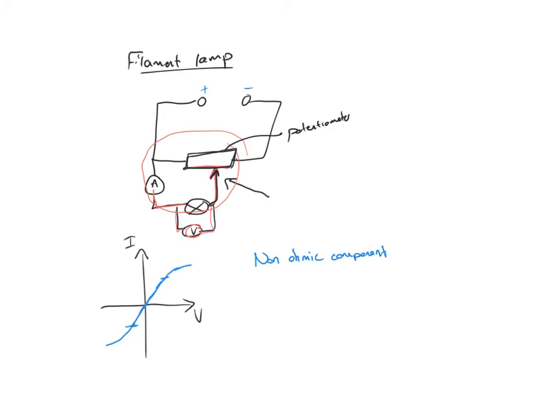And to remind you, filament light bulbs, so this is a filament bulb, they have a metal wire in them. So as we already said at the very beginning, the first half of this video, if you have a metallic wire or any wire in general, as time goes by, the temperature increases, which means the resistance increases because you have more collisions and so on.